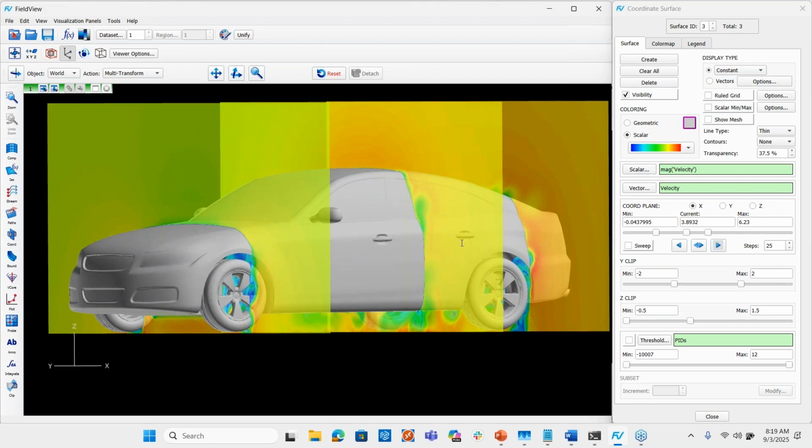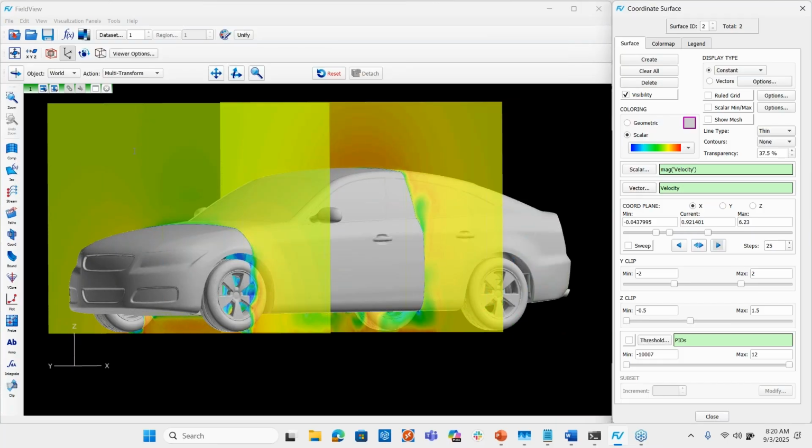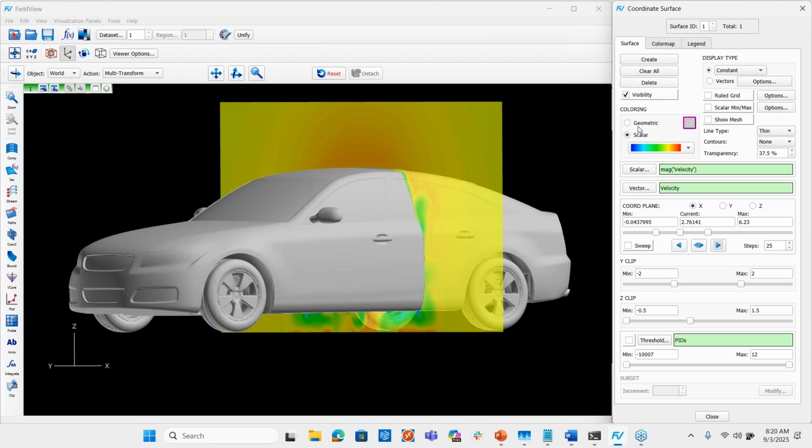And then now you can see all of our planes. And so now that I've shown you how to do this, let's get rid of these surfaces by deleting them. I'd like to mention that there's a feature called Quick Pick, which is done by just double clicking on the surface of interest, and that will select it, and then you can delete that. So if I double click back here, I just selected that surface, I hit delete, and double click here, Quick Pick that, and delete, and now we're back at the beginning. So really quick, let me just change these steps back to 100.